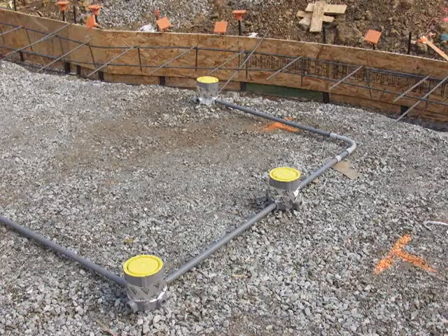In this building, the clients had requested floor plugs in the concrete slab. So we've gone ahead and laid our conduit and our 3 plug locations out on the floor and set up our boxes. The key with these boxes is to have them above the level of the slab. You do not want to finish them flush with the slab. If you finish them flush, it's going to be difficult to get all of the equipment in there and get it set up the way that you want it when it's all said and done.